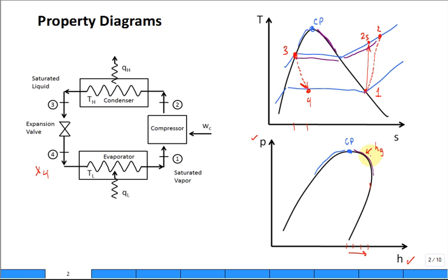But then it curves and it decreases. So why do we like pH diagrams, especially in refrigeration systems? Because this system naturally splits to a high side, pressure high, and a low side, pressure low. And often you just need 2 pressure gauges and you can tell a lot about the health of a refrigeration system.